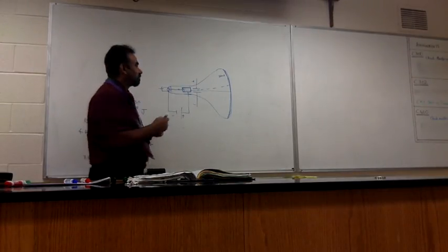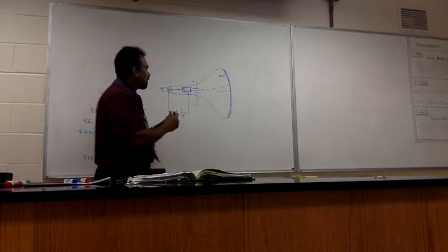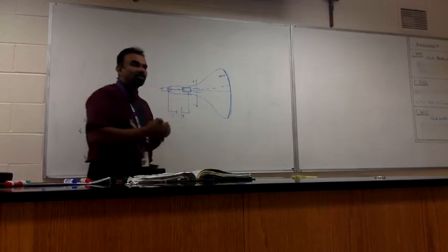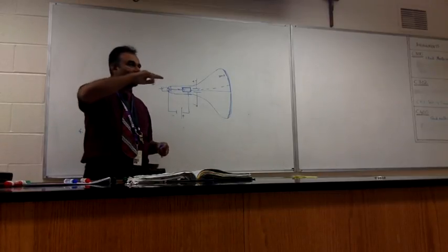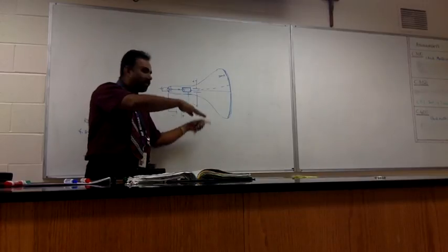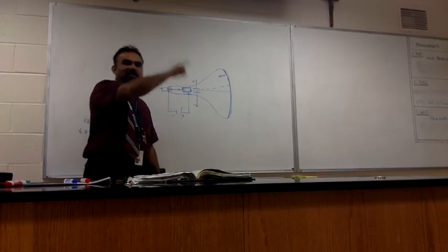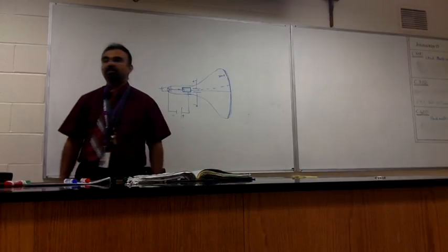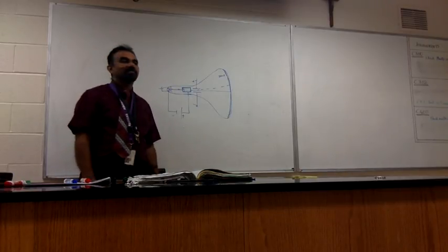It will go to the top when the cycle comes there, and the next cycle is when the bottom becomes positive. So what will happen is this electron beam that goes and hits the middle will get deflected to the top, then quickly will get deflected to the bottom, then again to the top, again to the bottom. Keep doing that. What will be seen on the screen? What will you see on the screen if this continues?